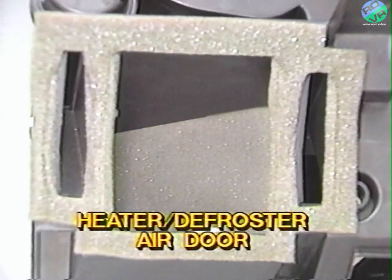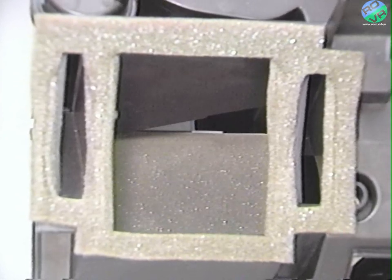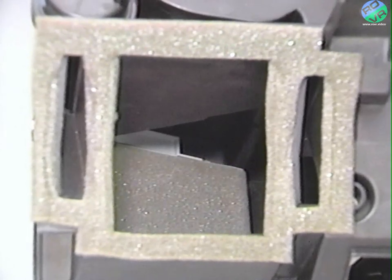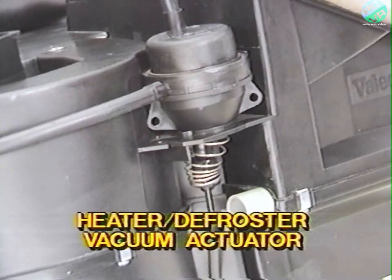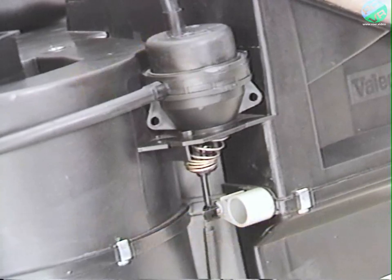The heater defroster air door also has 3 positions. In its fully retracted position, the door routes air only to the heater outlets. At mid-travel, air flows to both the heater and defroster outlets. When fully extended, the door routes air only to the defroster outlets. Like the mode air door, the heater defroster vacuum actuator has 2 vacuum lines connected to it. Both lines must have vacuum to move the door to the fully retracted position.